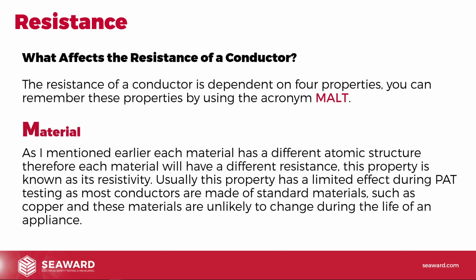Usually this property has limited effect during PAT testing, as most conductors are made of standard materials such as copper, and these materials are unlikely to change during the life of an appliance. So would there be a difference between a copper conductor and a gold conductor? Yes, there would. The gold would conduct better than copper. But from a PAT testing point of view, generally the materials we're going to come across, it'll be a copper cable, and that's not going to change.